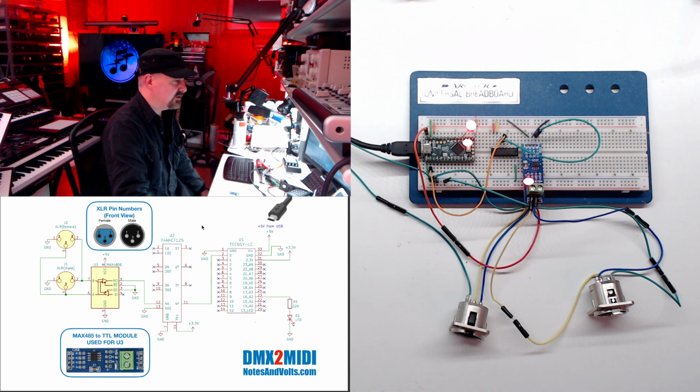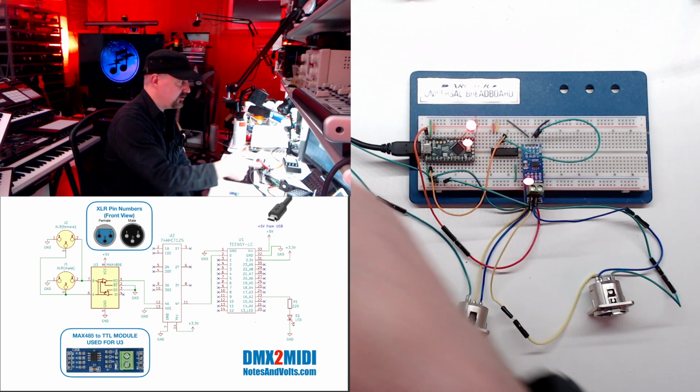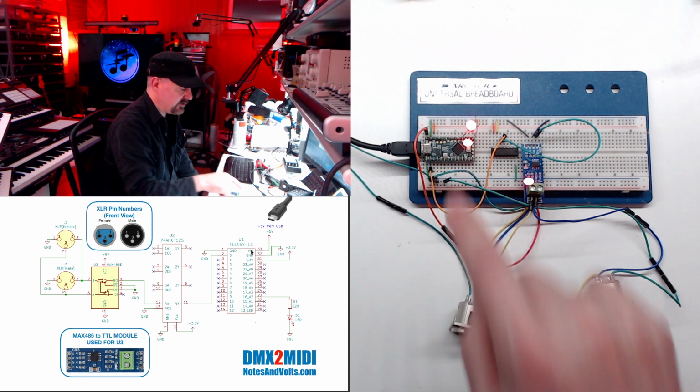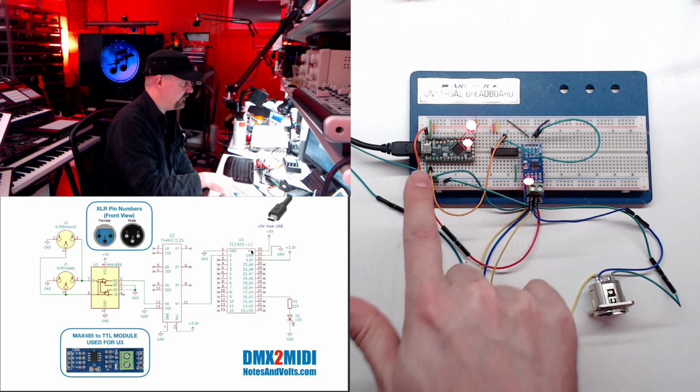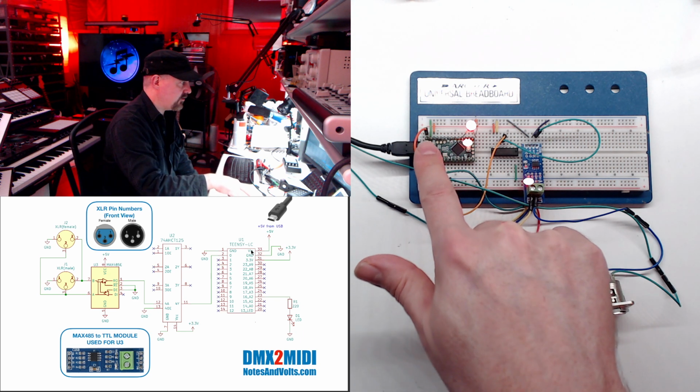our circuit. So you can see right here, we've got our USB cable coming in, and that is powering the Teensy and also transferring the data to our computer. The USB cable is going to give us 5 volts, and that's going to power our Teensy. Now, the 5 volts from the USB is also available at this pin here, the V-in pin, or as it's labeled on the board, the 5V pin. So that's going to give us our direct USB power out.